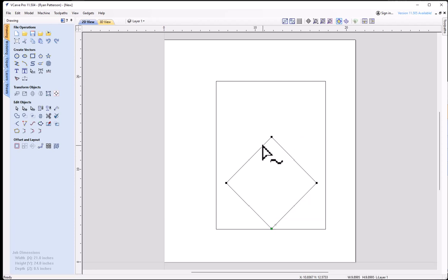And right-clicking over top of a line span, we get a different list of functions. And we have the to arc, and remembering the shortcut letter A. So right-clicking over the node, we get the functions for the letter D, and that is going to delete that point. And if we remember, that shortcut for the letter A is for an arc.